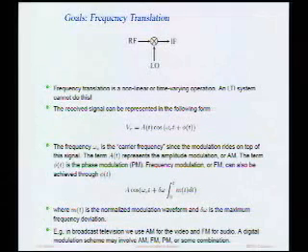100-something thousand kilometers. Okay. You can do math faster than I can, but basically it's simple. Lambda f is equal to c, where c is the speed of light. And so your antenna needs to be on the order of the size of the wavelength. So if you go to really low frequencies, the wavelength is huge. It's hundreds of thousands of kilometers at kilohertz. You can verify that. And so you have to build an antenna that's basically bigger than the Earth. Not a very practical situation.